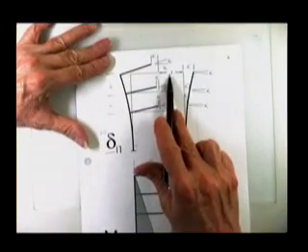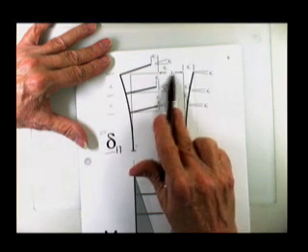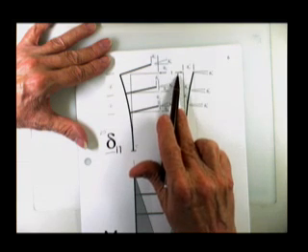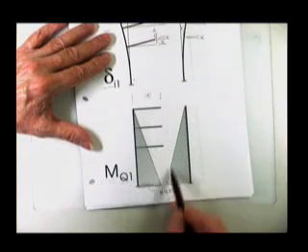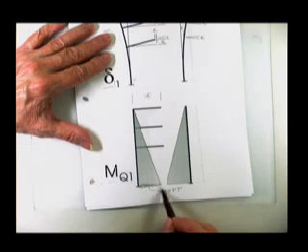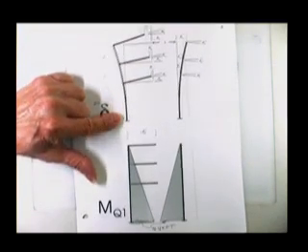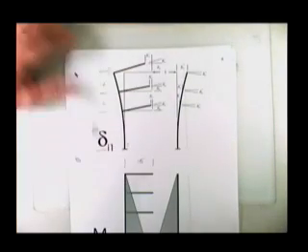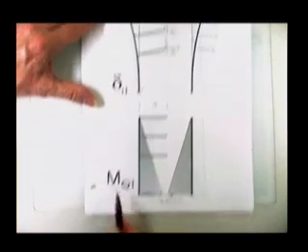Now then, because the one applied to this, you had to let him put his feet on something to generate that force. This is what his feet did. Now his feet moved to the right, causing a moment diagram on the tension side of the vertical member, and it happens to also be 44. It didn't have to be. The two legs didn't even have to be the same length, but they both got a 1 on them, and they're both 44 feet tall. And therefore, there's the moment diagram due to a unit load in the number one direction.